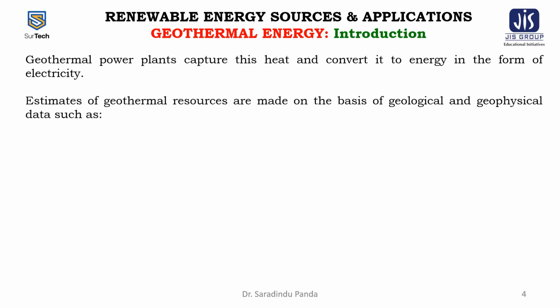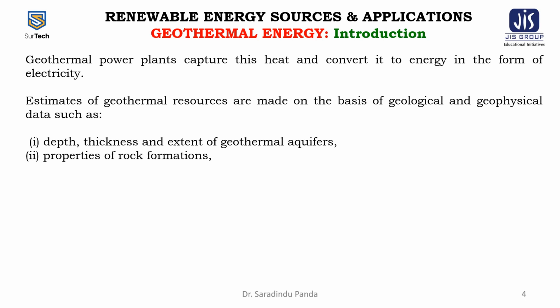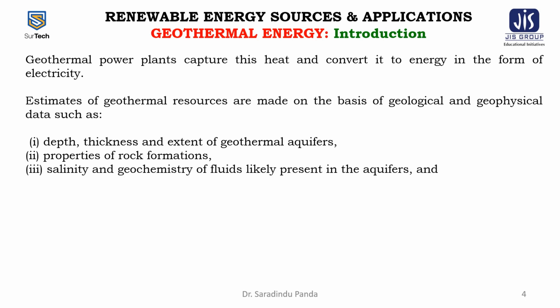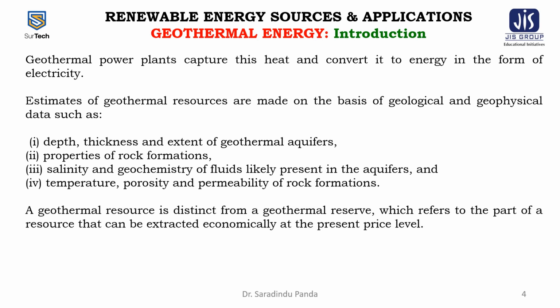Estimates of geothermal resources are made on the basis of geological and geophysical data such as depth, thickness, and extent of the geothermal aquifers, properties of rock formations, salinity and geochemistry of fluids likely to be present in the aquifers, and the temperature, porosity, and permeability of the rock formations. A geothermal resource is distinct from a geothermal reserve, which refers to the part of a resource that can be extracted economically at the present price level.